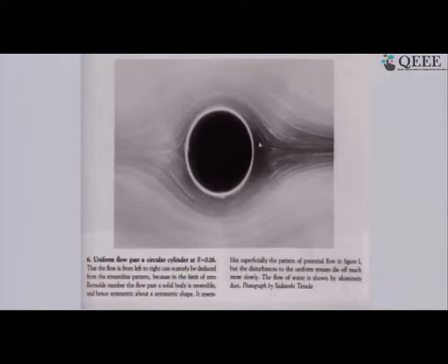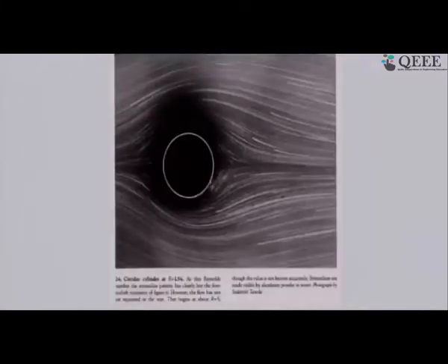But this part is slightly bigger, so that means the wake of the cylinder, this is what is called the back portion of the flow, which is called the wake. This is not symmetric to the front portion. This is something that has begun to happen, and this will continue more pronounced as the Reynolds number increases a little more. Now we are looking at this picture where Reynolds number is 1.54.